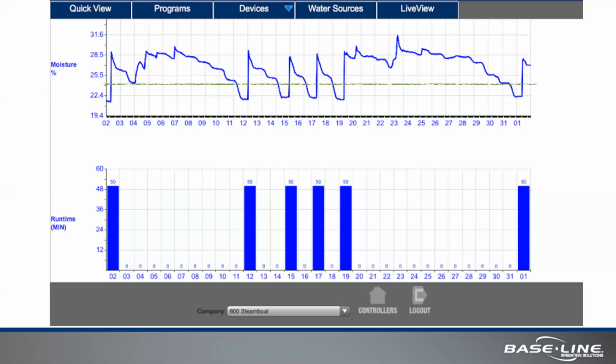So in this system, a lower threshold strategy was set at around 24%, and anytime a start time came up on the controller, if that moisture content was below that threshold setting, then it would allow the irrigation system to come on and operate for whatever time was programmed on it, and all other zones that are linked to that sensor would operate in the same manner.